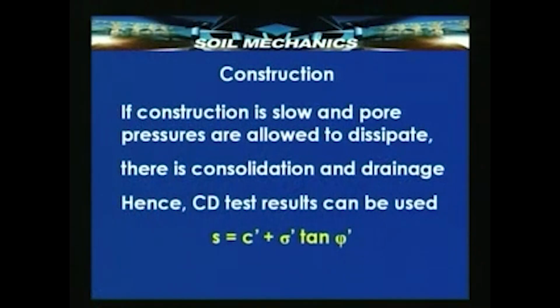Let us take a look at what kind of shear strength test needs to be done and what shear strength parameters need to be used under these construction, drawdown and long term conditions. It is interesting to note that each one of these corresponds to a different set of drainage conditions, and therefore different test results have to be used.